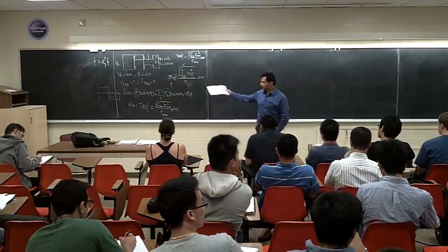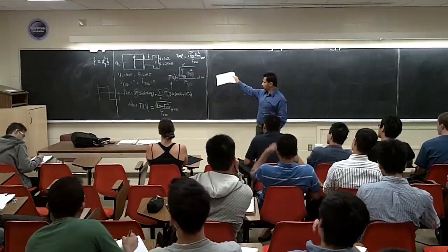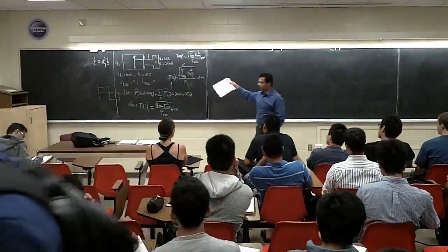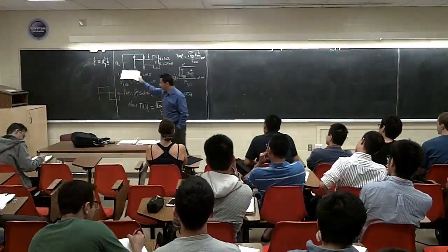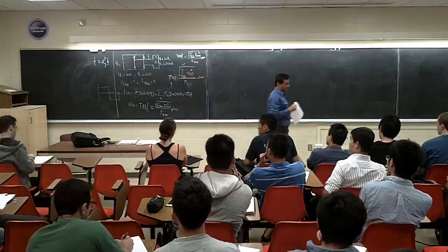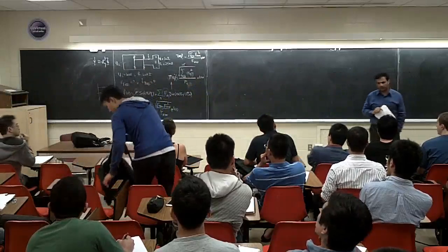Now, it says for this inverter, we have RL load, 10 ohm resistor, 25 millihenry inductor. We have RL load like this. The DC bus is 100 volt, and this inverter is a 60 hertz inverter. It said calculate the voltage THD and current THD. Why? Are they different in the THD?